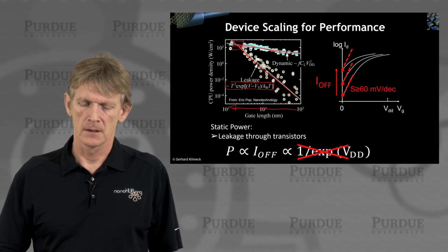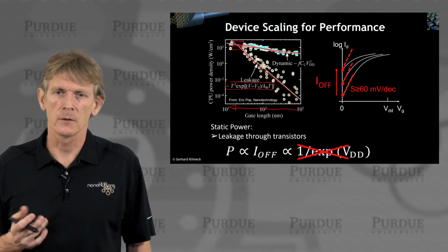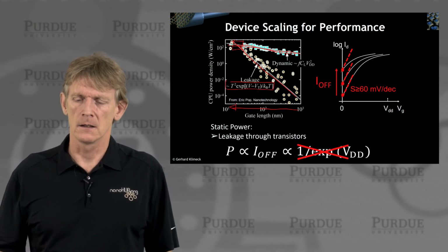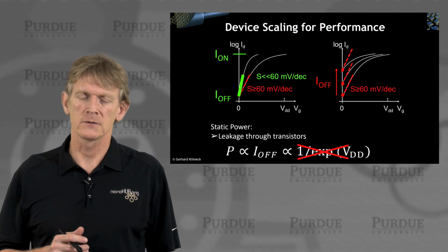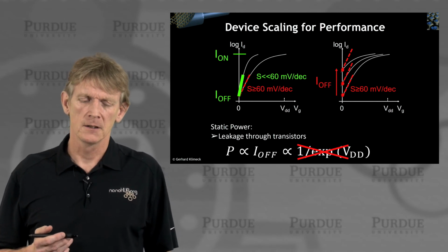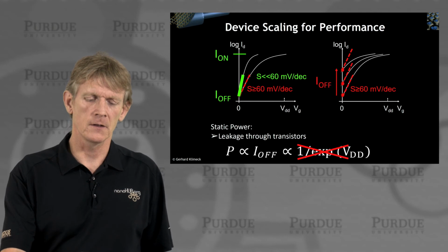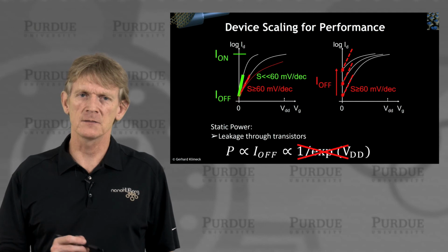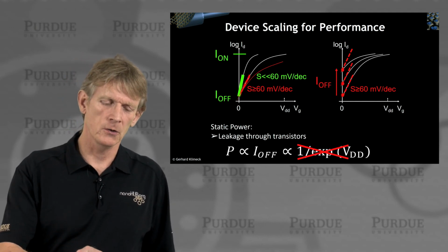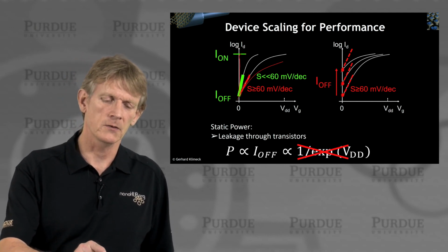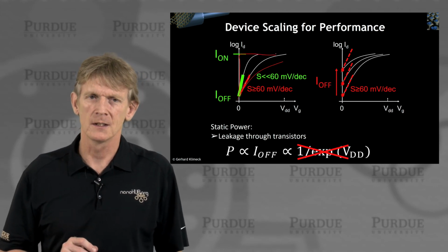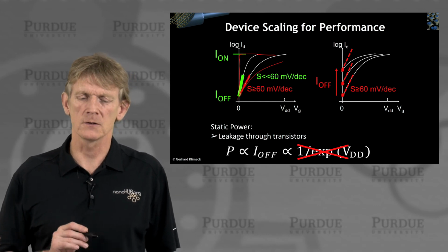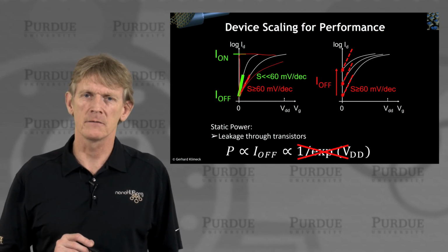Why is this device consuming so much power now? Okay. So the question is, how do we get away from this exponential dependence, right? We would like to have switches that consume less power. So the ideal thing would be to have a switch that is not limited to this slope here, and in reality actually looks more like this. Think of this as being a spaghetti that you can push over, and you'd like to have, in the ideal world, a switch that looks like this, right? So you can reduce the slope. You want to reduce this sub-threshold slope to less than 60 millivolt per decade.